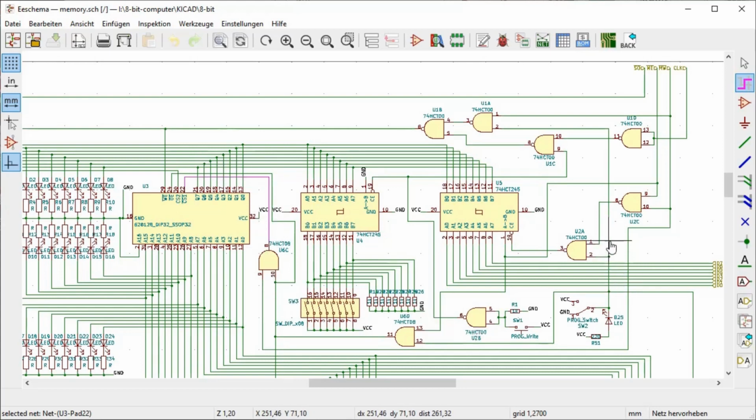If we switch to manual mode, that line gets connected to ground, so it is low, and that blocks the write signal from the control logic and also blocks the bus transceiver that connects the RAM chip to the data bus, since a 0 on the input leads to a 1 on the output, and that blocks this transceiver completely.